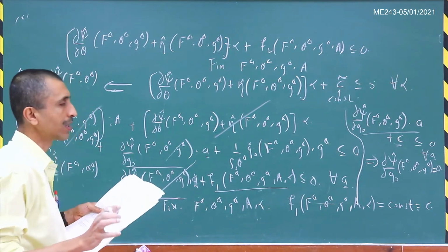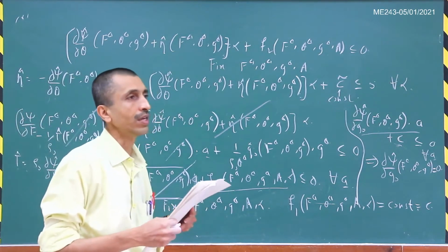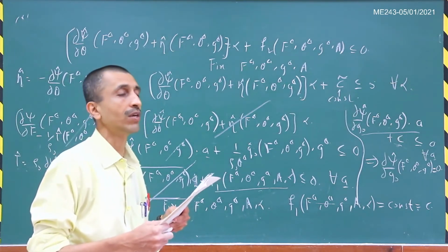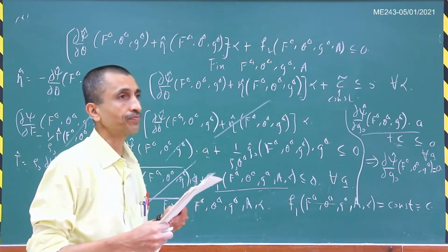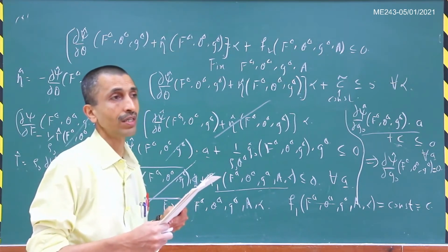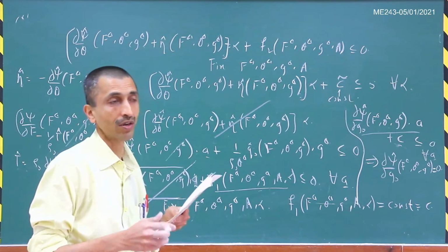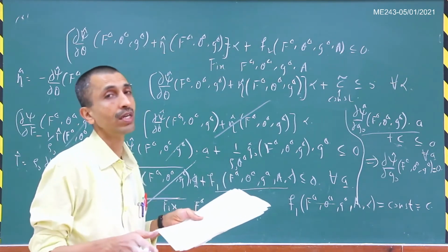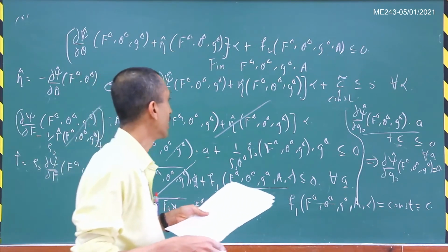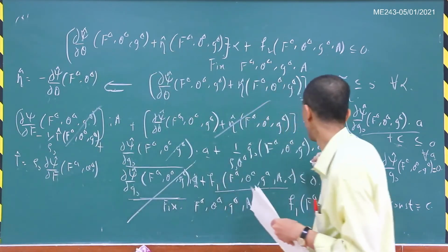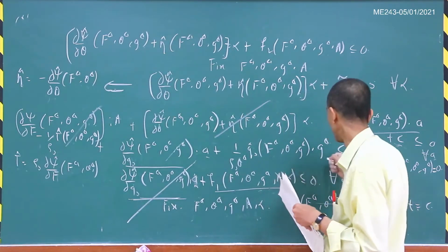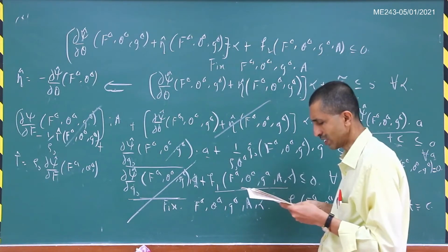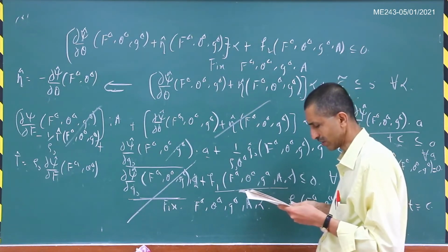So to summarize, basically what we have shown is that as a consequence of the second law of thermodynamics, the free energy function, the first Piola-Kirchhoff stress and the entropy functional cannot depend on the temperature gradient, and in addition the temperature gradient and the heat flux satisfy this particular inequality, as a consequence of the second law of thermodynamics here.